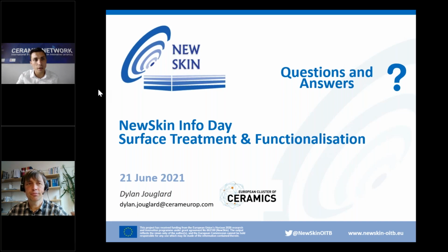Okay, and could it be measured in this case? Of course, measuring stresses, it depends. Typically we would use a witness piece like a thin silicon wafer that mechanically bends or buckles, and then it's possible to measure the deformation of this thin substrate. Otherwise, measuring strains or stresses is not straightforward. But it can be measured, for instance, this way with a witness piece.